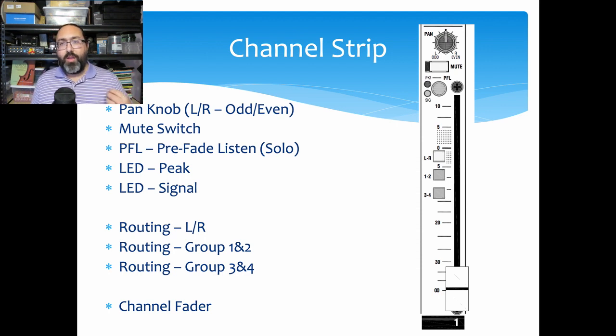If I remember correctly, on Rick's demo of the console, he actually turns the gain up way too loud just to demonstrate this overload. If you ever have a channel that goes red, turn the gain down. It has gone too hot.